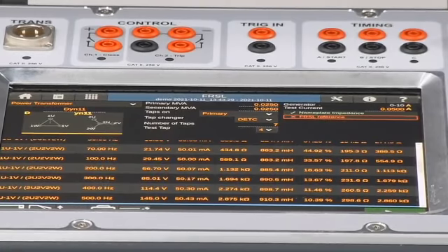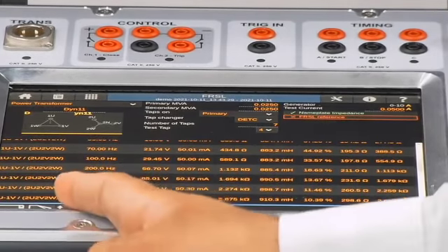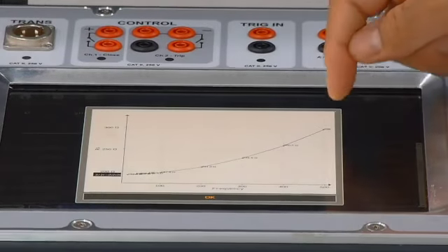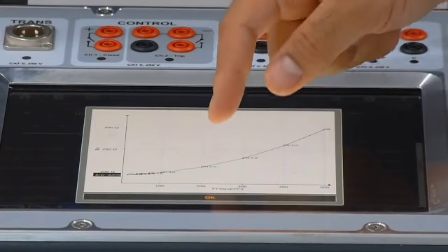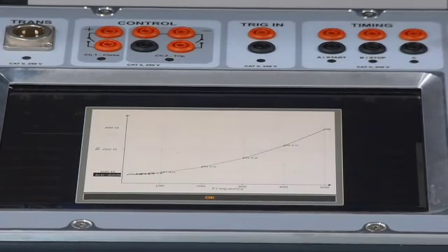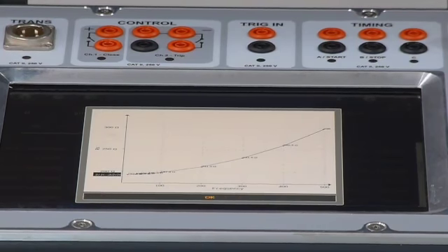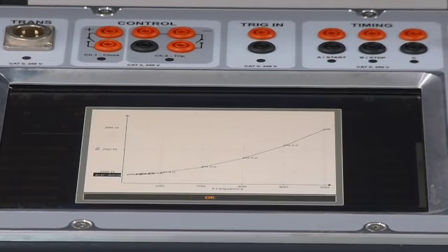I am sufficient with 50 milliamps to show the full graph details, which is this graphical representation between resistance and frequency, which I need to compare every time I measure. Maybe this year, maybe after some years, when I start comparing with the previous results, or from previous years, I can also compare and see if there is an increase in the resistance at higher frequency.